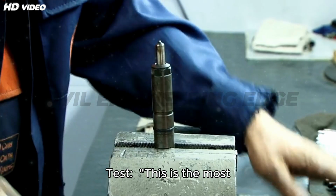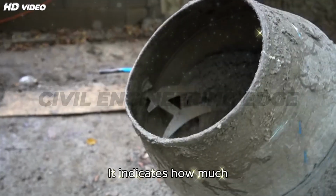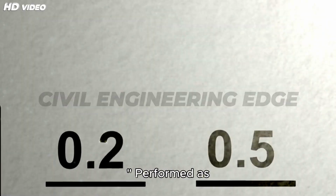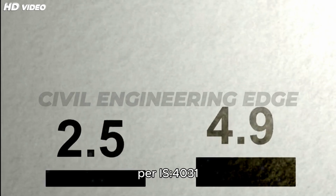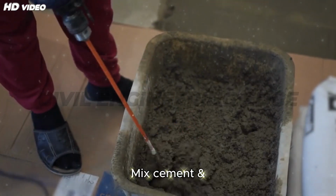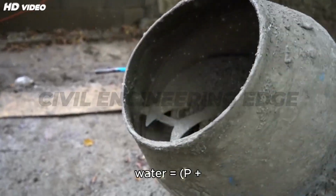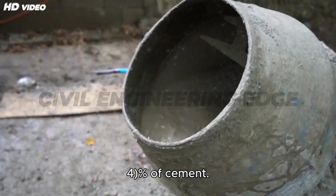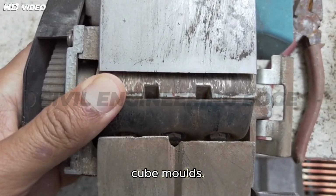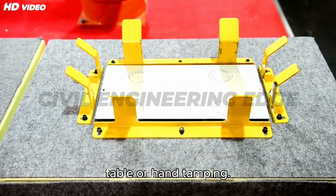Compressive strength test. This is the most important mechanical test for cement. It indicates how much load concrete made from this cement can bear. Performed as per IS 4031 Part 6. Procedure: 1. Mix cement and standard sand in 1:3 ratio. 2. Add water equal to P over 4 plus 3 percent of cement. 3. Fill into 70.6 millimeter cube molds. 4. Compact with vibrating table or hand tamping.